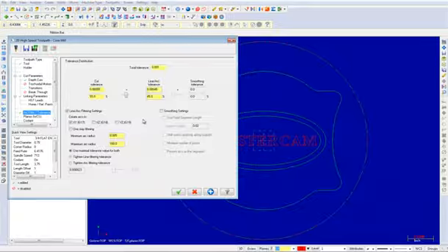Line arc filtering settings allows you to activate line arc filtering for the toolpath and apply the settings you define in this section to the toolpath refinement. Toolpath filtering lets you replace multiple very small linear moves within the filter tolerance with single arc moves to simplify the toolpath. Smoothing distributes a toolpath's node points, avoiding the clustering and grouping of points that can cause marks and other imperfections. And finally, Create Arcs In creates arcs in the selected plane. Your post-processor must be able to handle the arcs and output the code G17, G18, G19 to select this option.